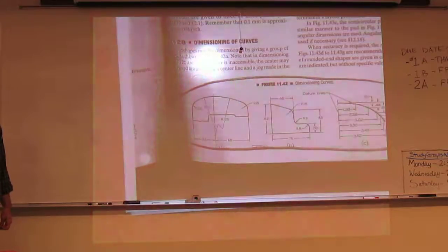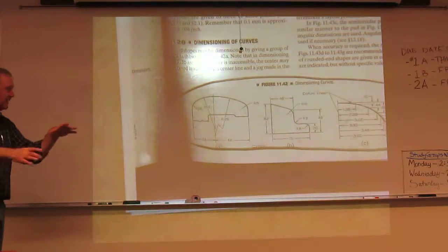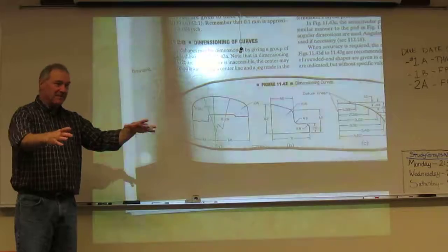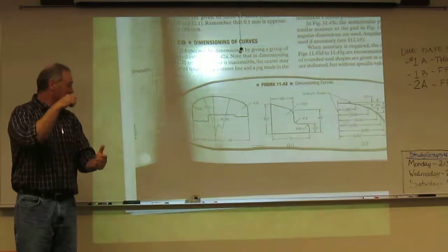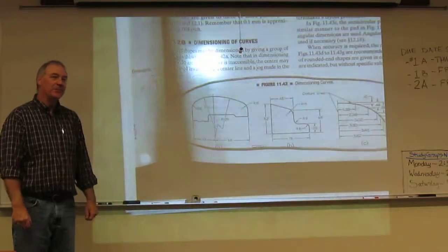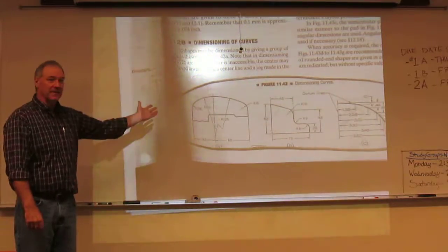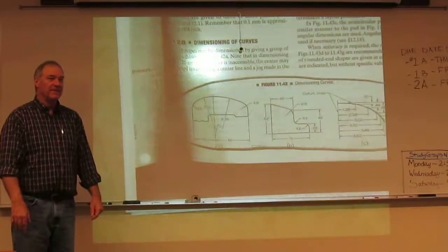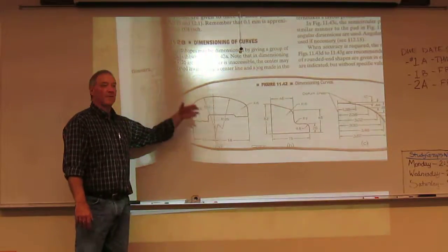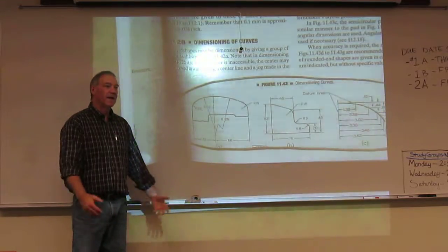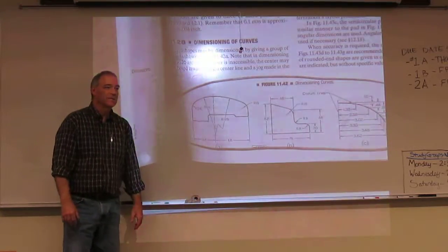They draw it right on a piece of, if it's steel, they got a piece of sheet steel sitting there. They pull out a marker for steel and they start drawing. They redraw this stuff right on it so that they have a line to cut along. If it's a CNC machine, the CNC machine will basically find a zero and then cut it for you. It doesn't need the lines because it's doing it internally, digitally.